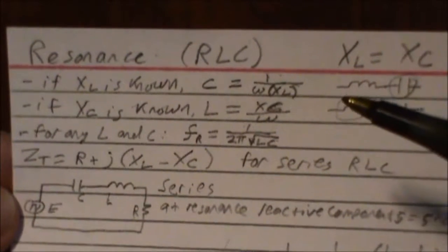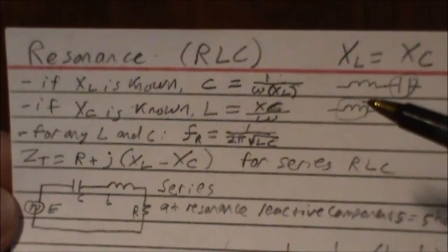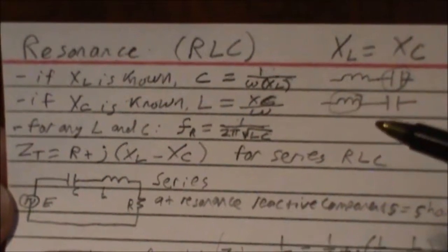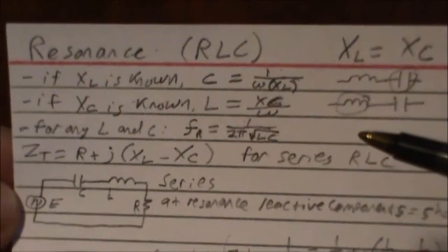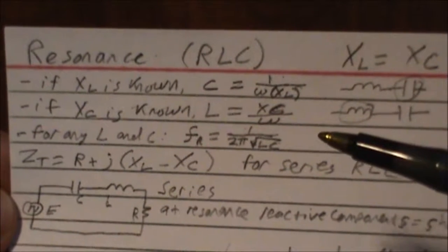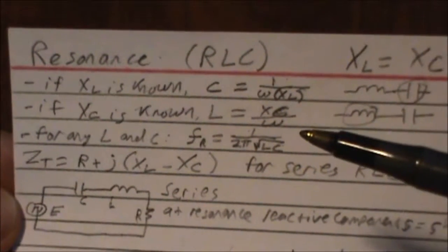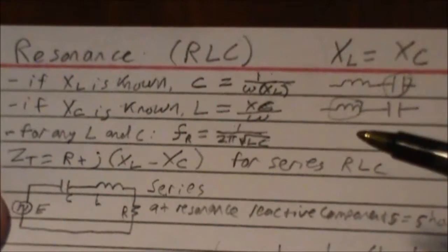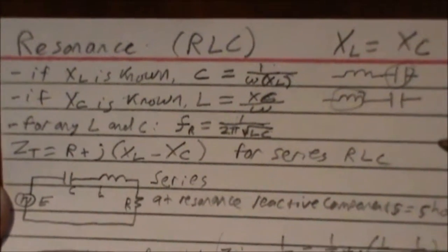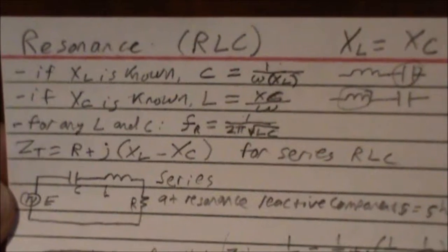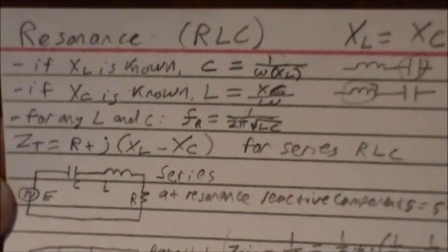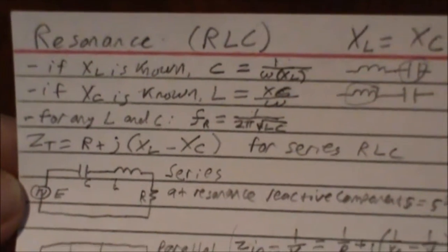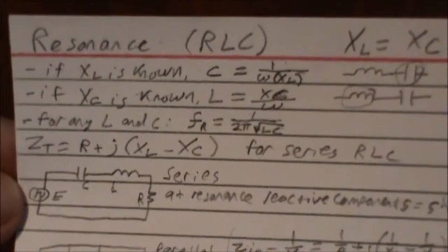And of course there is a resistance in the coil, because it's a coil, a length of wire. There is some DC resistance, related to the Q factor, which we'll get to in a bit. But in a very well-made coil, the Q factor is often so high that it affects the resulting part values very little.